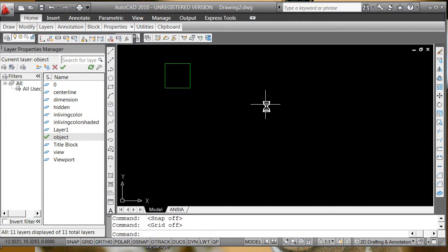So right now the snap and the grid are not on, and to review, I could now arbitrarily draw a line from here to here, and hitting the space bar to finish, because the snap and the grid were not on when I did it, it'll give you issues, it'll give you problems, it'll give you conniptions. Unless, of course, you know that you can change the snap and the grid in the middle of a command. So, for instance, here, I can turn them all on, all off, all on, F7, F9 together. It's a really key skill if you're going to be using the grid.